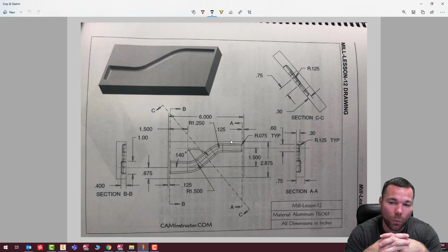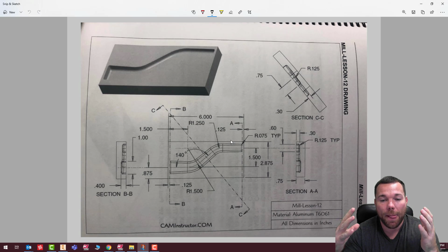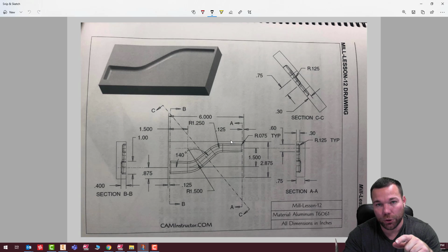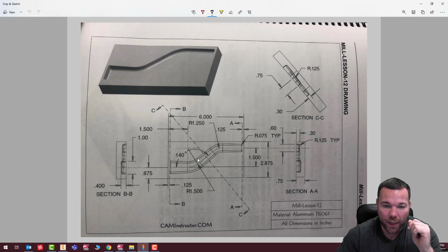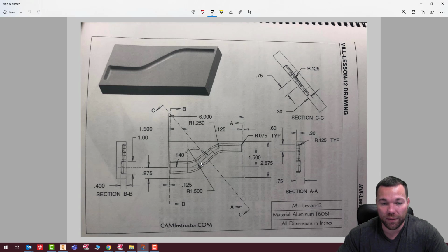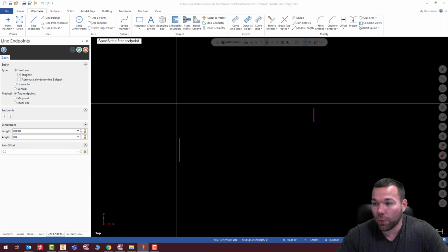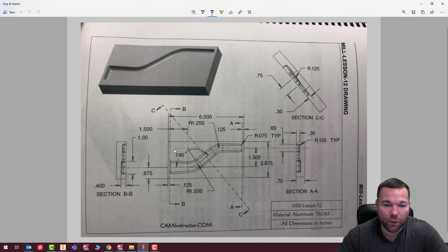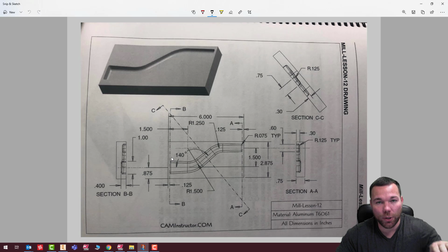When it tapers like that, an equal amount consistently down to a size, that's when you want to use one line to extrude it. If I wanted to control that taper, maybe it tapers more here in this first inch and then it doesn't taper at all for the rest of it, then I would do 2 lines and I would create exactly how I wanted it to taper. In this case, I only want to do 1 because I want it to taper equally the whole way down. So for the exercise, you actually need to create 2 lines and use 2 paths.